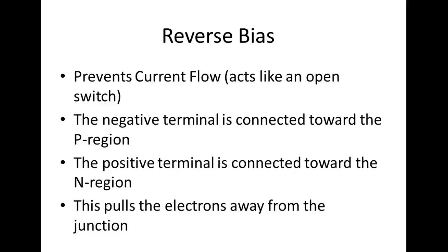Now you have to understand, when you put enough voltage across everything, you're going to have current flow. So this guy is going to have a rating called the breakover voltage. We never want to exceed that, because that means you're going to force current through the reverse bias diode, it's dropping a lot of voltage. It's going to produce a lot of heat real fast. And what's it going to do?